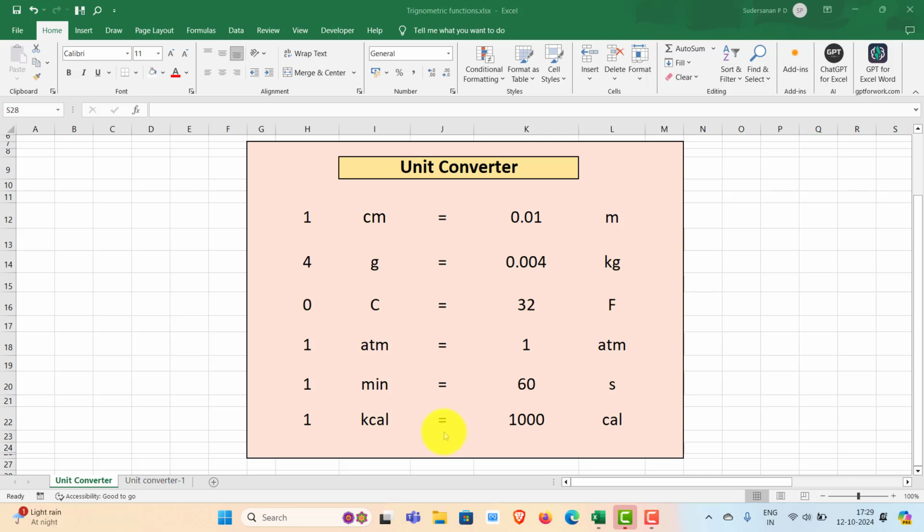Now I'll explain how to use this function. Let us say we have to convert from feet to meter. Here I have that unit conversion for length. Here is the number of units you want to convert. Say for example, I need to convert 5 feet into meters, so you can select feet from here. So you are getting 5 feet is equal to 1.52 meter. If you want some other unit here, say inch, 5 feet is equal to 60 inch.